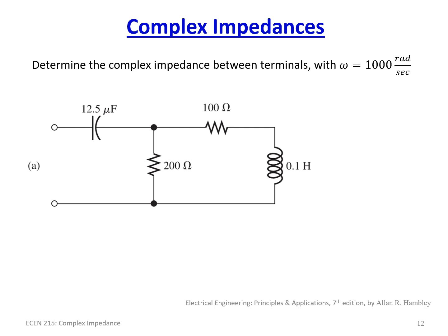So if we do that, we have omega is 1,000 and 12.5 microfarads. So we're going to first focus on the rectangular form. So omega is 1,000, so 1 over 1,000 times the 12.5 microfarads. So take 1,000 times 12.5 e to the minus 6 farads. And then we just simply need to do 1 over that. And we end up with minus j80. So we'll go ahead and write that down. And I'm going to have a slide where I show this in a second.